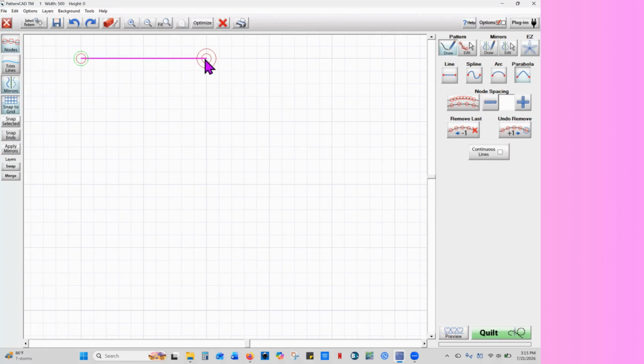I left clicked and dragged to this point, but now I wouldn't have to left click anything. I could just bring my cursor, my arrow, to where I want the next point to be and tap. I would have to put continuous line on there. Tap, tap, tap. And boom, just like that, I have some straight lines. So snap to grid works great for squares.